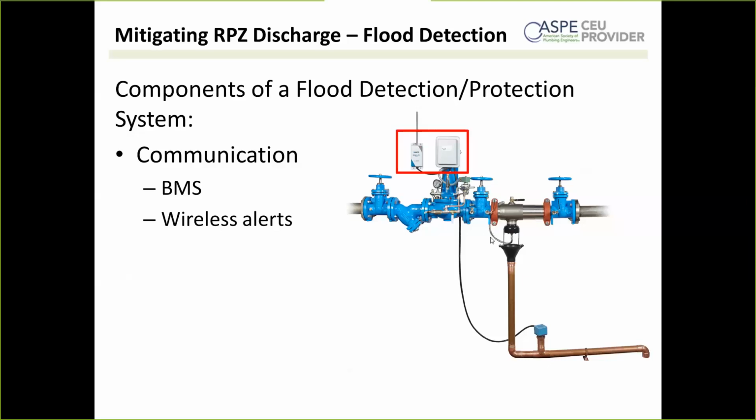I mean, theoretically, sure. It's not how they come right now, so you kind of have to jury rig your own thing, and I would not recommend that because in general, messing with any part of a backflow preventer that's not manufacturer approved is not a good idea, right?